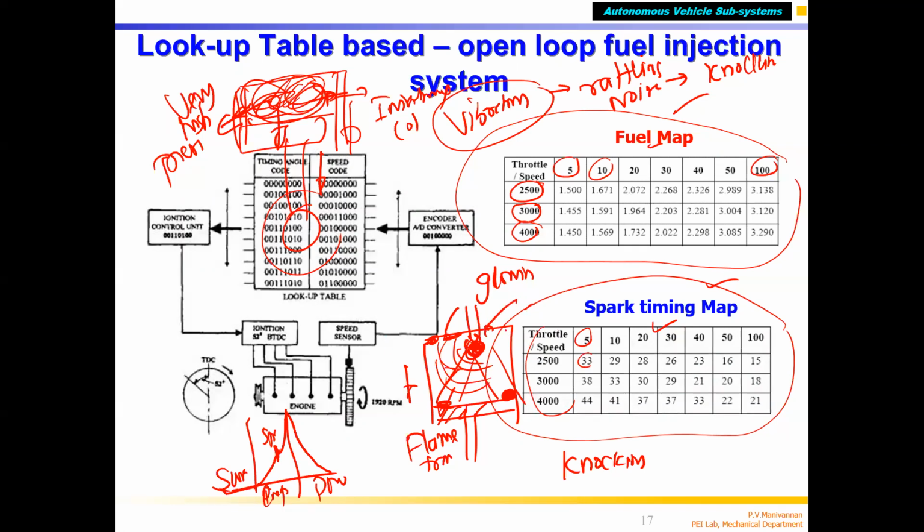Next time, when new fresh air comes, even before you give the spark, the fuel will be ignited because the carbon deposits are glowing in hot condition. They absorb some amount of the fuel from the previous cycle, and when fuel is there, they will burn it. These carbons are burning at a high temperature, around 1000 degrees. So when the fresh air-fuel mixture comes during suction, nothing will happen. During compression, because the valve is closed, by the time the fuel has mixed, combustion will start at several places, even before you give the spark.